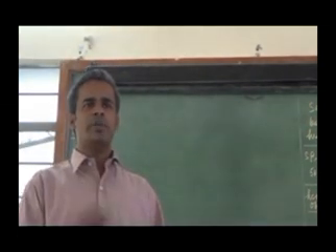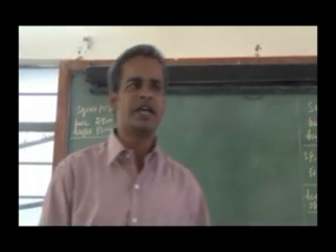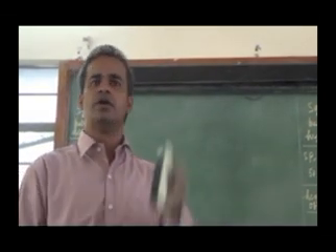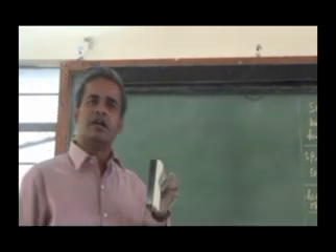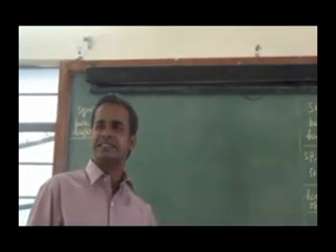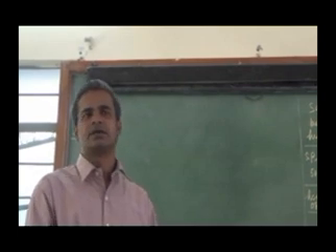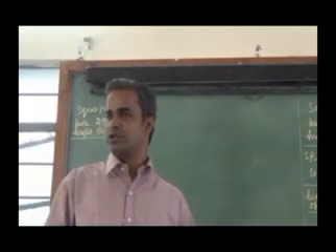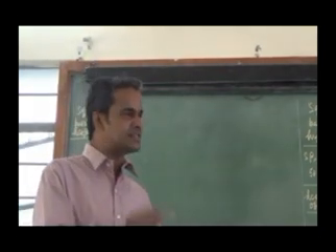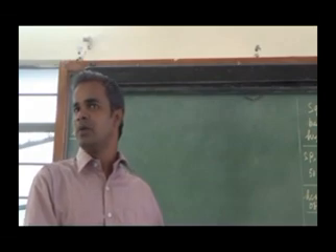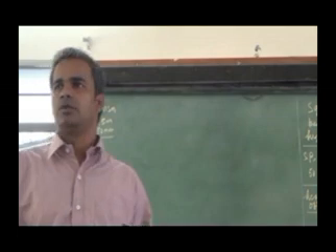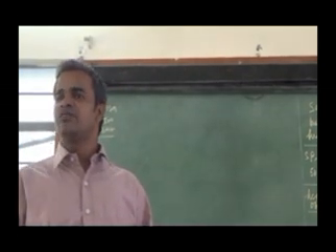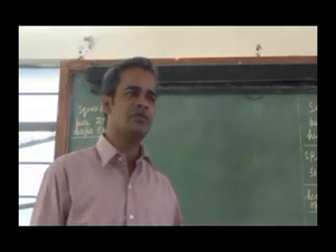Face. What do you mean by face? A square prism has a base and face, right? Vertical face, rectangular vertical. It is kept vertically like this, and the face is parallel to the picture plane. Remember, see carefully, the face is parallel to the picture plane and 10 mm in front of it.